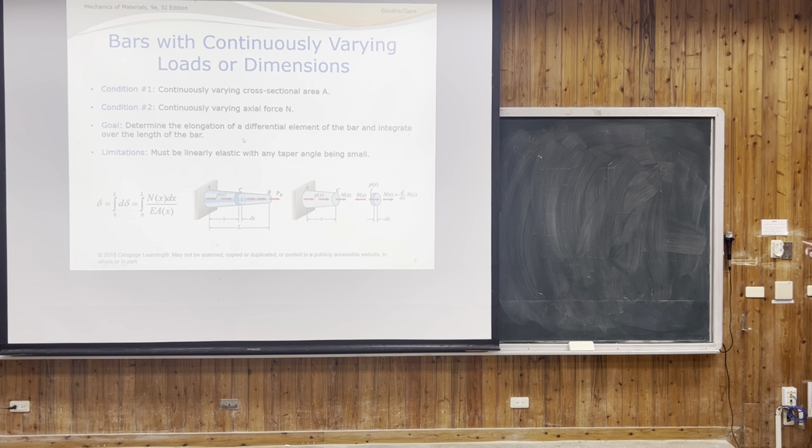And we come to these kinds of questions, where the shape or the volume differs along the length, right? This is basically the same concept. We didn't change any concept. The idea is that we write the force or the area as functions, and we integrate. After the integration, we get the sum of elongation. Everyone's okay? Yeah.